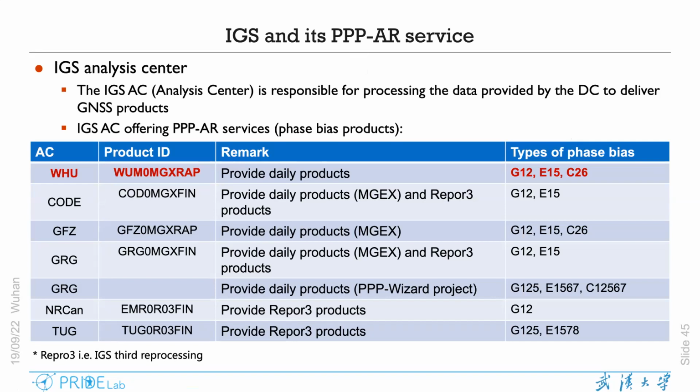So there is a question about the reference frame of each constellation. Of course, if you are going to use the broadcast ephemeris from each constellation, for example, the GPS broadcast ephemeris and the Galileo ephemeris, these two systems have clearly different reference frames. So you cannot directly use them to do the positioning, especially in the standard point positioning.